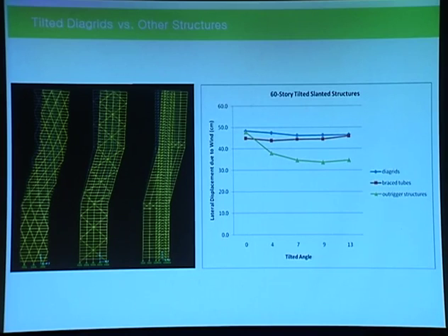A stiff braced core, then outrigger trusses, and mega columns. Initially, they don't make this mega truss-like triangulated configuration. But if you tilt the building, then these three major components, the braced core, mega columns, and outrigger trusses, make very large mega trusses. That kind of impact adds lateral stiffness, as you can see in this graph.